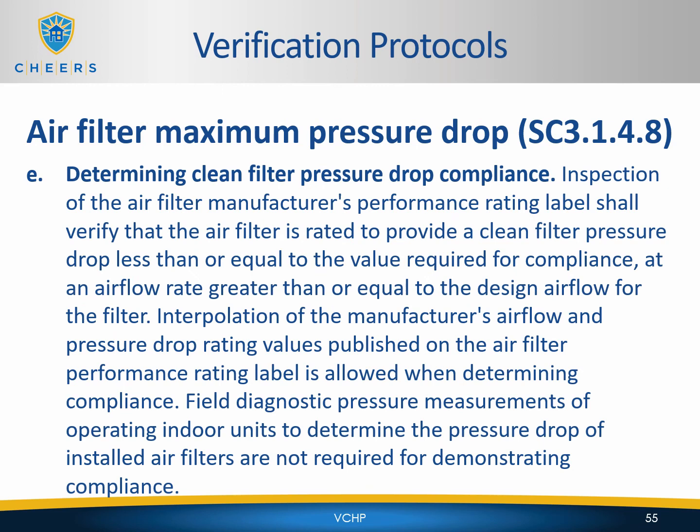Determining clean filter pressure drop compliance. Inspection of the air filter manufacturer's performance rating label shall verify that the air filter is rated to provide a clean filter pressure drop less than or equal to the value required for compliance at an airflow greater than or equal to the design airflow for the filter. Interpolation of the manufacturer's airflow and pressure drop rating values published on the air filter performance rating label is allowed when determining compliance. Field diagnostic pressure measurements of operating indoor units to determine the pressure drop of installed air filters are not required for demonstrating compliance.